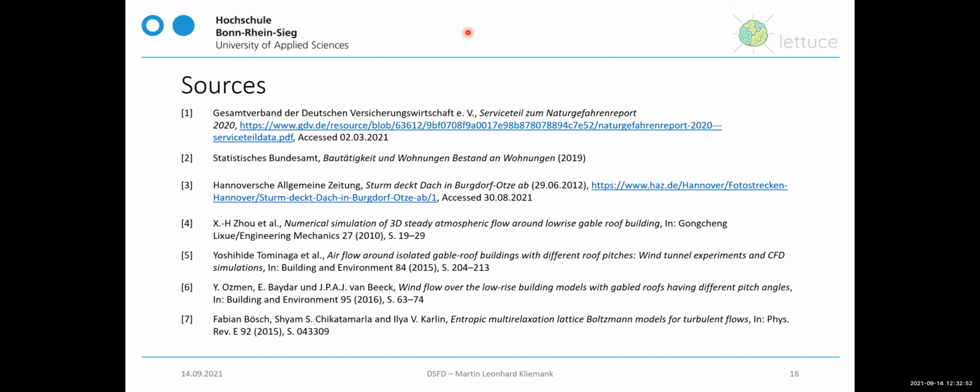I see. Okay, there is another question. KBC formulations usually suffer from dispersion issues at moderate to high Reynolds numbers. Did you observe this issue in your simulation? So, spurious vortices appearing in the shear layers, for example?